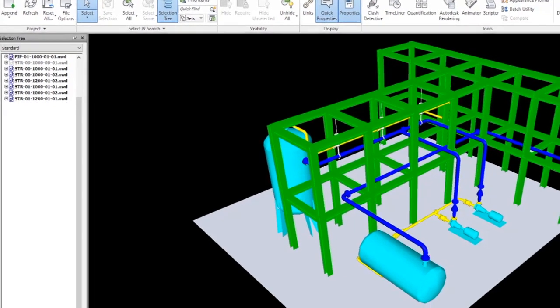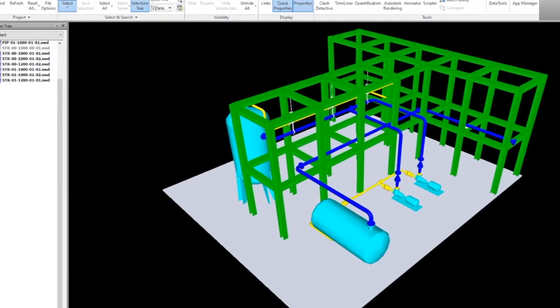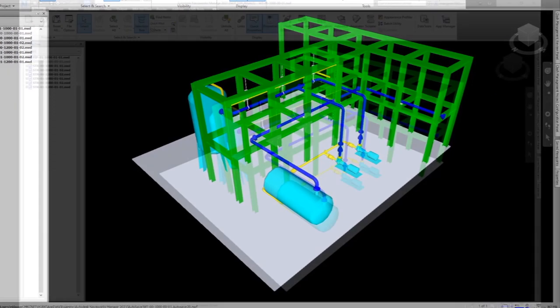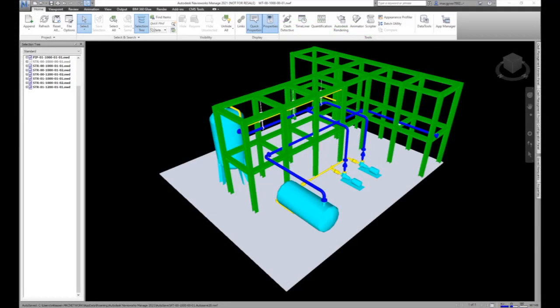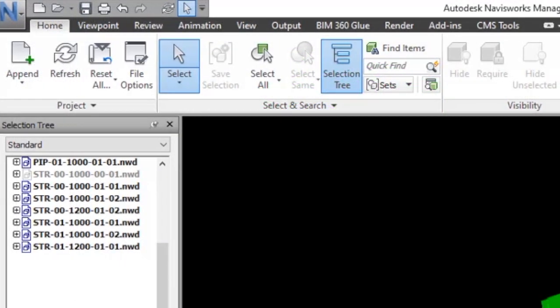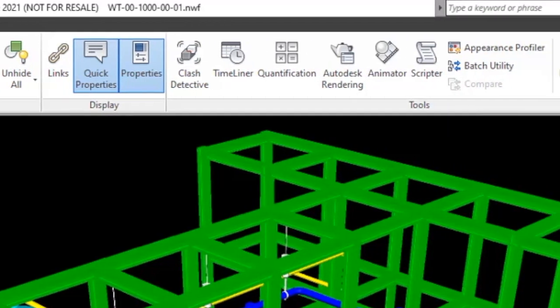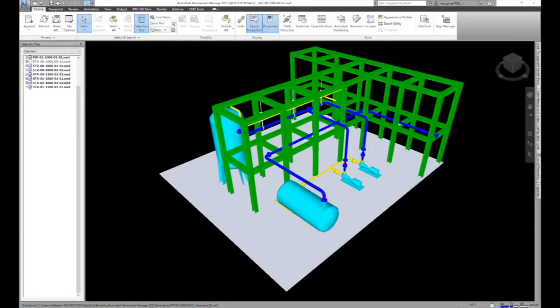Number 2. If data tools are used to display database properties, NavisWorks performance will be considerably degraded depending on the size of the database. A more efficient option is to generate the NWD files overnight for use in the walkthrough. These NWD files are then isolated for the duration of the clash review, where they are not affected by changes to the live models. In addition, database properties are embedded in the NWD files, eliminating the need for NavisWorks to query the database during the process. The NavisWorks Batch utility can be used to generate the NWD files.